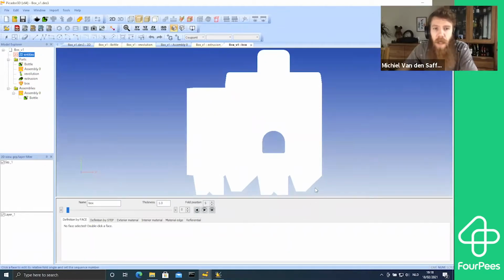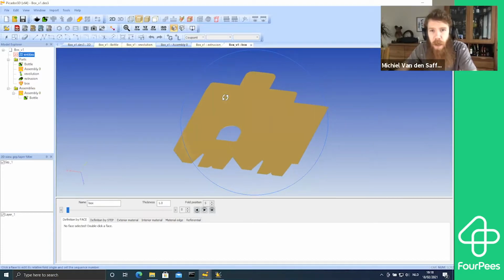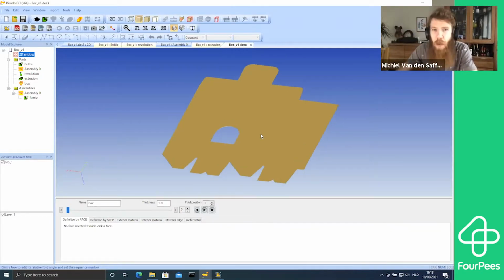If your technical drawing is nice and accurate, so all the lines connect properly, all the cut lines connect where they should connect, then immediately you'll get a nice piece of cardboard the way you want to see it. If your drawing comes from, for example, Illustrator, and two lines aren't perfectly attached, you might sometimes get a little bit of error messaging. And then you'll have to take the box back to 2D or use the 2D drawing tools we have available here to fix whatever's wrong.